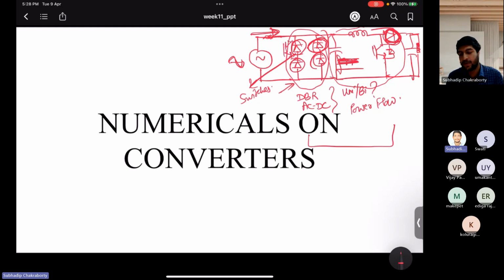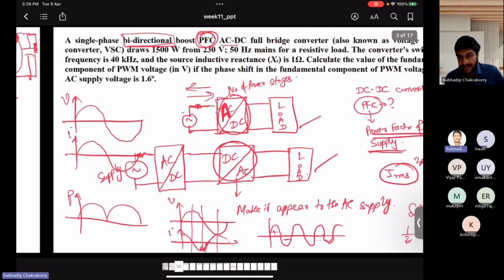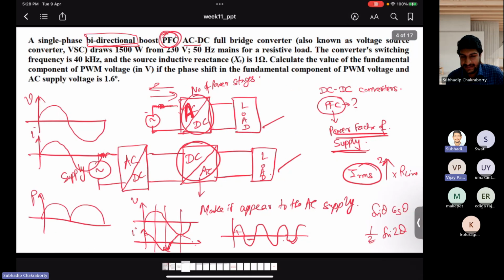A body diode, or anti-parallel diode, is necessary such that you can conduct the current or the power in both ways. So that's how we can make the devices or systems bidirectional, along with achieving power factor correction. Both can be done. You can do power factor correction for unidirectional as well as for bidirectional. But for bidirectional, the additional advantage is that your device is more controllable and you can utilize the power stored in the battery, or the loads can have regenerative action, right? So that it can support the supply.